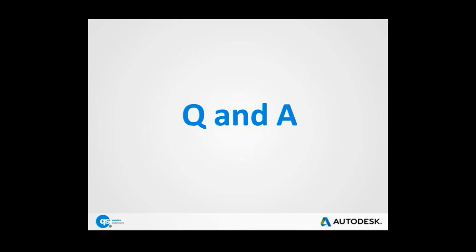Right, okay. And just as well, in terms of the licensing, as I mentioned before in the presentation, everyone, Nastran in CAD is a network license only, so it can be shared between multiple seats. But do you know at what point it borrows the license from the server? Because you've got the Nastran tab in there. When you click on that tab and you bring up the environment, it then takes that license from the server. I typically would keep it until Inventor's shut down. Right, so you borrow it and it takes a license from Nastran, and then when you close Inventor, it sends it back to the server. Yeah. Right, okay. That's useful to know.